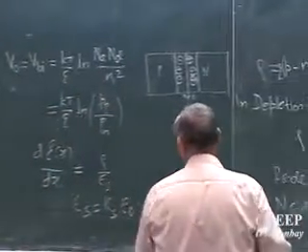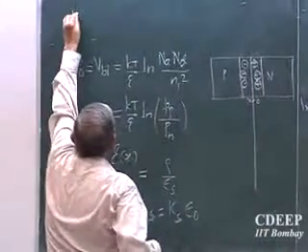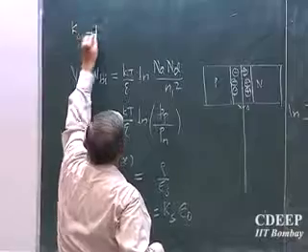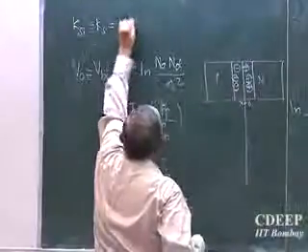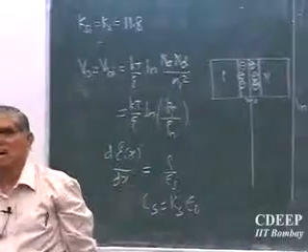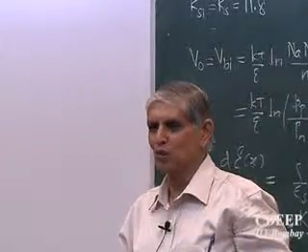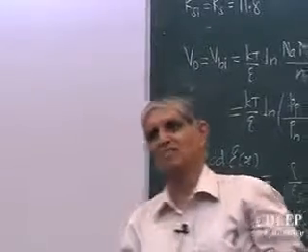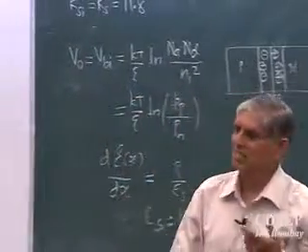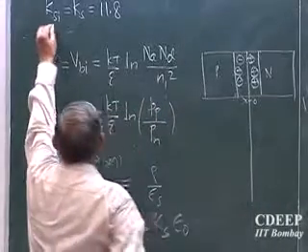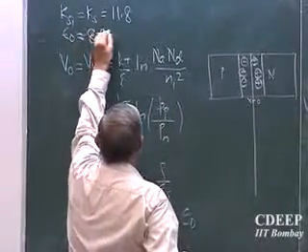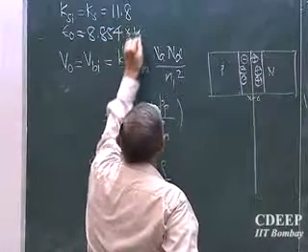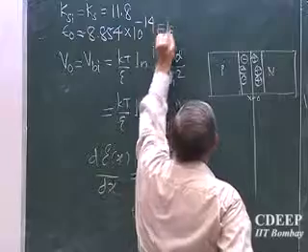In the same way, epsilon Ks, this Ks value for silicon, which I will only say Ks, is 11.8. Some books may use 11.9, some may use 12. Whatever number I give you, that's fine. Is that clear? Some measurements show it is 12, some show it is 11.9. I believe most books take 11.8 as a good value, and that's what we use. Epsilon 0 is 8.854, and if you want the third decimal, 10 to the power minus 14 farad per centimeter.